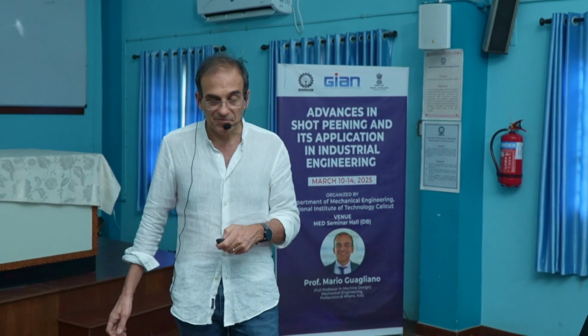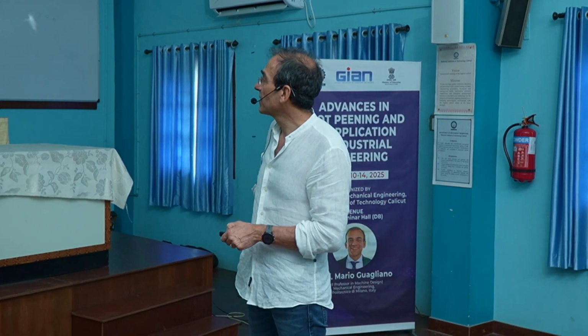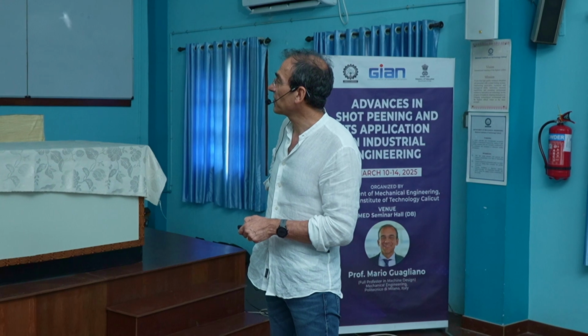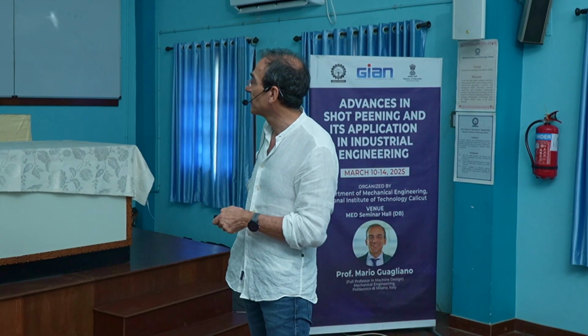Some comments: the affected depth is around 1.5 millimeters. We need calibration tests. It's good if knowing the sign of the residual stress is enough. For high levels of stress, the signal could be saturated, so we do not appreciate any variation anymore.